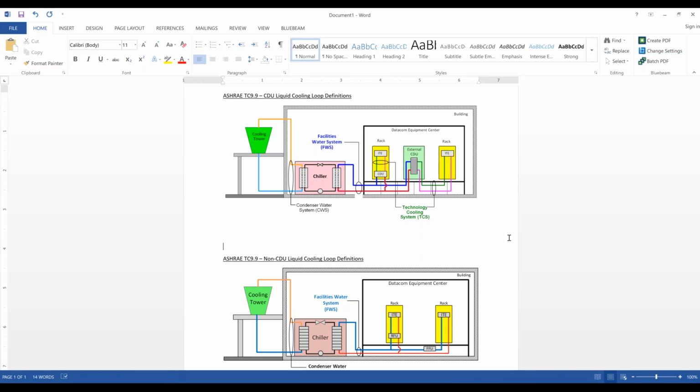In the example of having a CDU, the diagram that I showed at the top, which is a CDU-based liquid cooling implementation, what's currently being referred to as the FWS, or facility water supply, system is very much the same, in my opinion, for cold plate and for immersion or rear door heat exchanger. That path from facility cooling to the CDU. So I think that's an area where we should have a harmonization between wetted material specs and probably a few other things. What do you think about that?